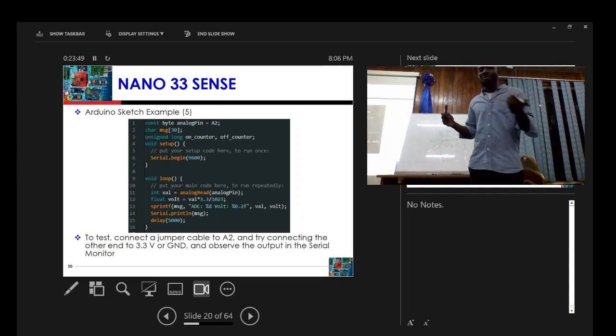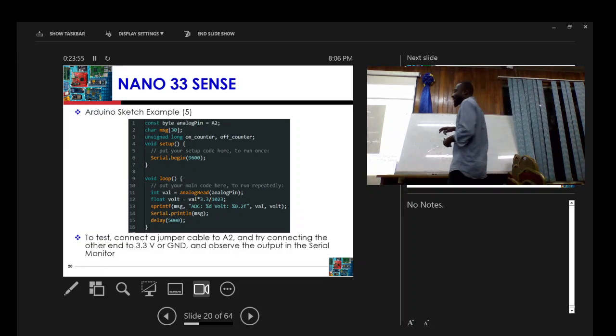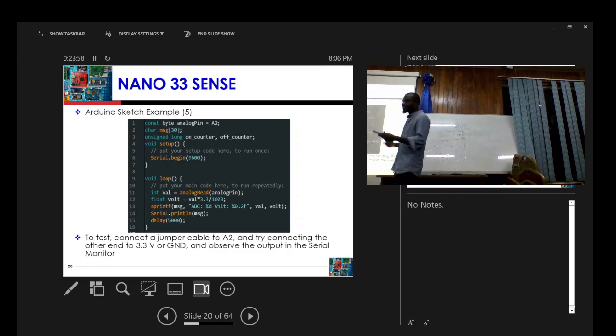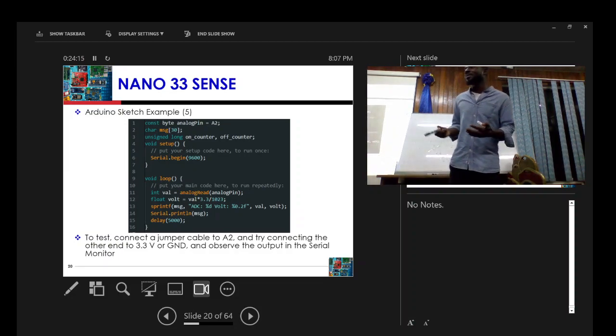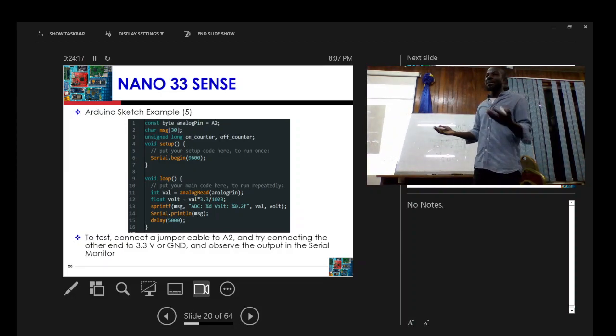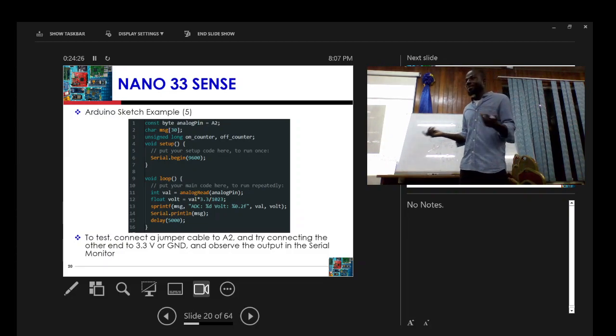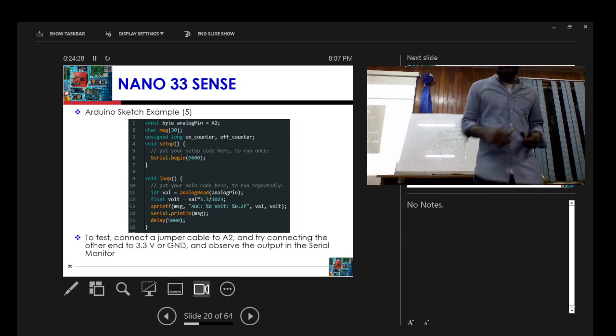What makes Arduino programming easy is that everything is a library, and then you call a function within the library. If you don't understand it, say I take this code and it has analogRead and I don't understand, I just have to Google analogRead, and it will bring out the Arduino page that explains what analogRead is and how to use the function. It's as easy as that. So you can just go and try all the other codes out. Understood? Yes, sir. All right.